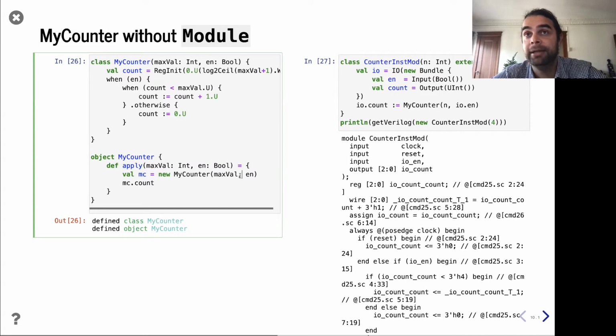Before, we had purely Scala functions and then these Chisel modules, and we were very deliberately making a Chisel module that has Scala arguments for parameters, but internally is all Chisel. Now we're blurring it. We can have a Scala method or a Scala class that returns some Chisel pieces. We can actually take in Chisel pieces as arguments, they're first class citizens. So you can start seeing a bit more of that flexibility.